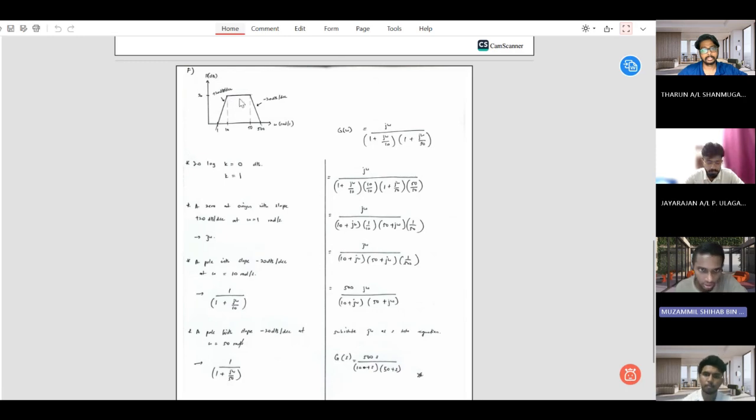We can see that at omega 10 radian per second the slope changes, giving 1 over 1 plus j omega over 10 for the pole with slope negative 20 dB per decade. All right, I will pass to Satthia for the next explanation.